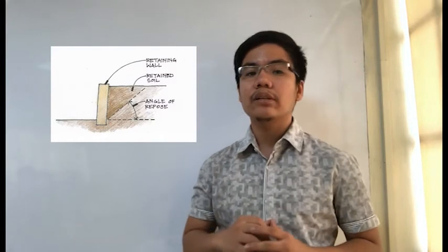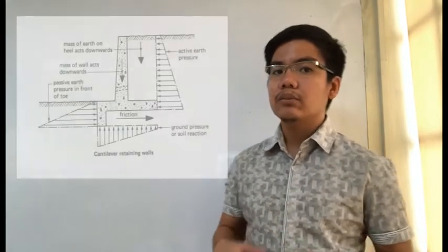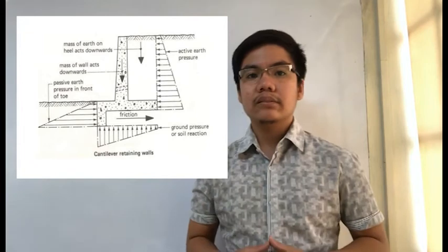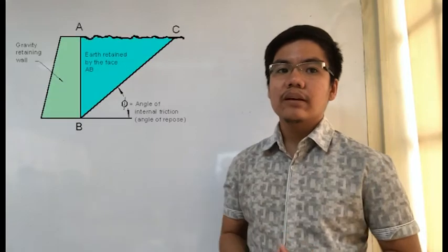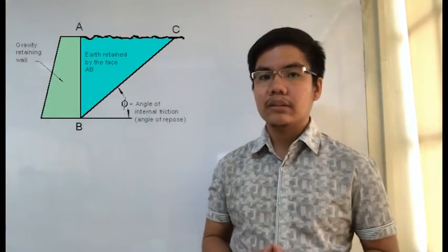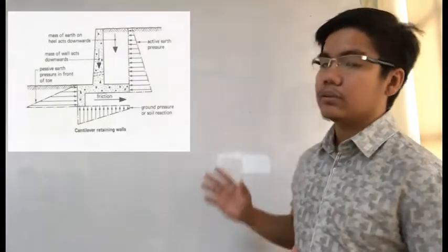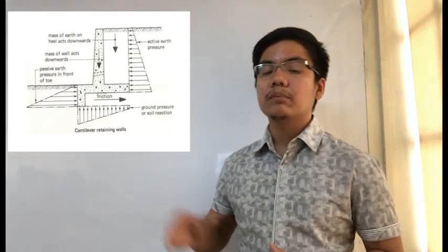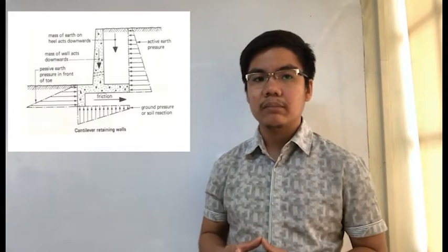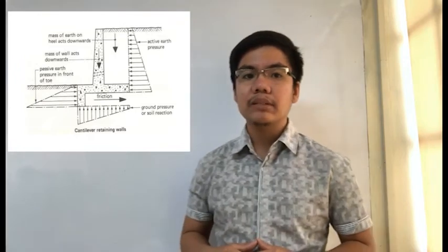The most important consideration in proper design and installation of retaining walls is to recognize and counteract the tendency of the retained material to move downslope due to gravity. This creates a lateral earth pressure behind the wall, which depends on the angle of internal friction and cohesive strength of the retained material, as well as the direction and magnitude of movement the retaining structure undergoes. Lateral earth pressures are zero at the top of the wall and increase proportionally to a maximum value at the lowest depth. Earth pressures will push the wall forward or overturn it if not properly addressed.